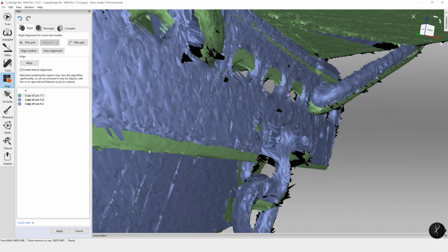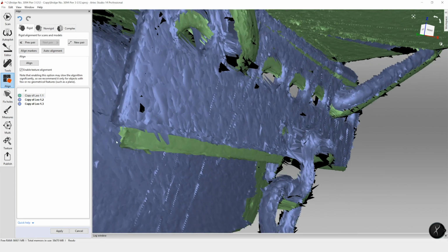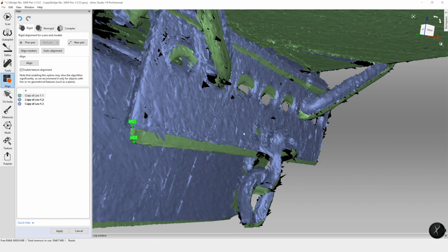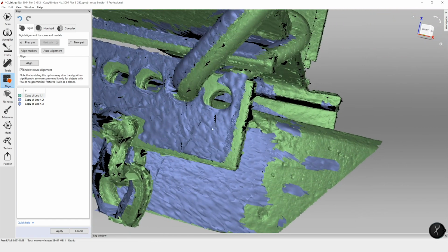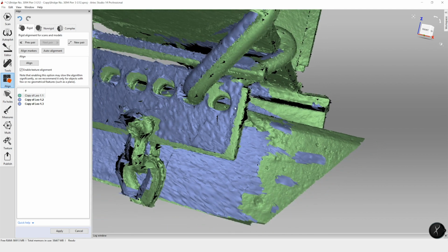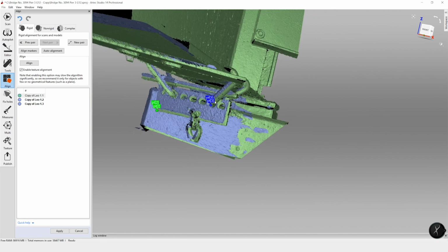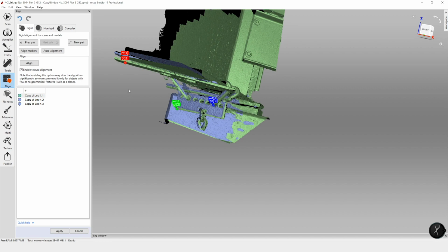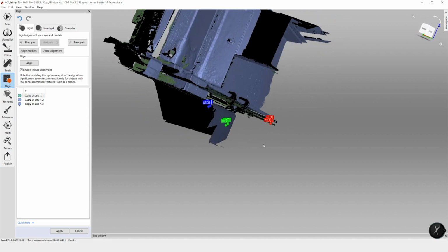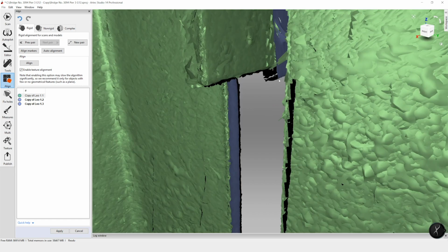Using the different visualization tools is very helpful when we're trying to see the model from a bunch of different angles. So colors, you can change these colors as well to make them anything you want to make sure there's a clear difference. One of the nice things about this process too is you can add additional points as you go. So if you need to make finer adjustments, you can do an initial align of the markers and then add more points and continually align. And we're also able to go in and then remove some of those points. So you can go in, bring the alignment a little bit closer, then remove all of your points and start again. So you have some options for this process.